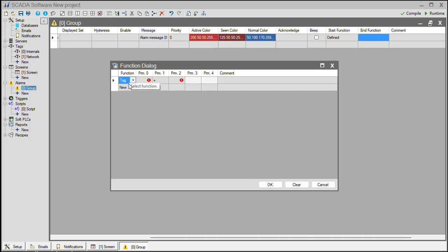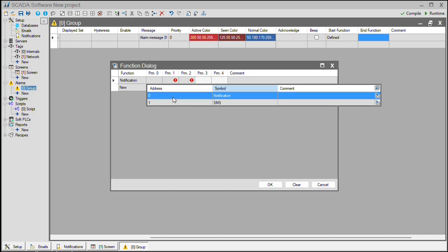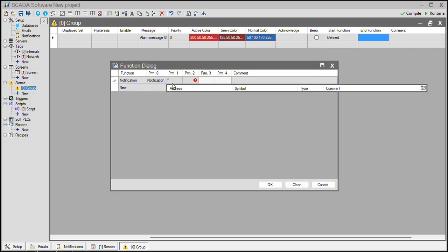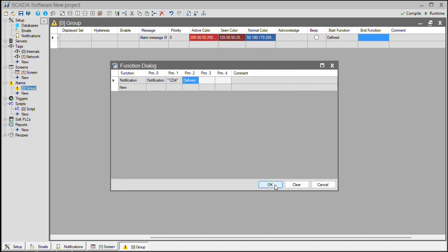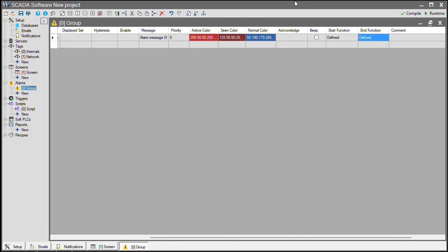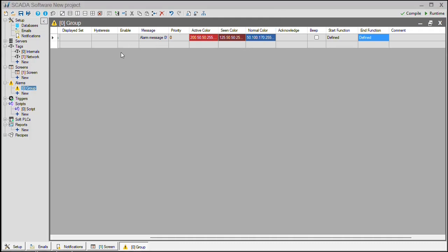When the alarm goes away, that is, when the condition creating the alarm disappears, let's send a message to the operator again. We enter the chat ID here again. We can send a message like normal this time as content. We don't have to select a description or tag. We showed sending messages via alarms on the screen.